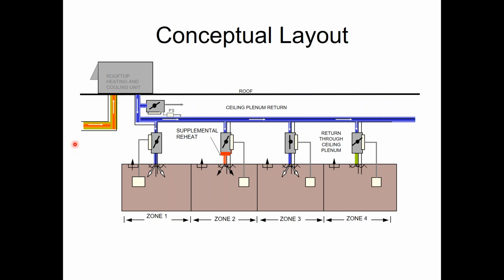I don't know if inlet guide vanes are specifically prohibited on code, but VFDs are required in most scenarios. As you saw before, anything above 65,000 BTUs of cooling has to have a VFD on it. So at that point, you're not going to buy a VFD and guide vanes. So the guide vanes are essentially eliminated by the energy code requiring the VFD. So yes, essentially.